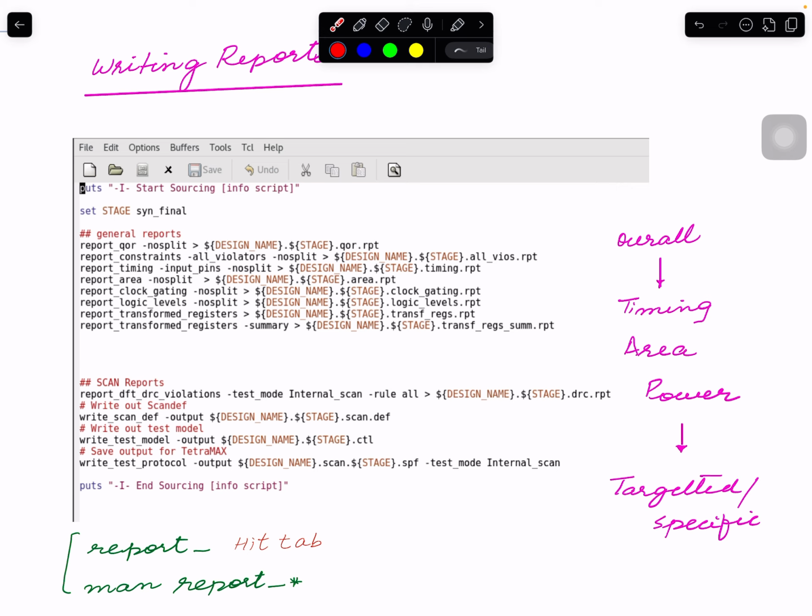Internal paths mean paths where input and output ports are not involved. Okay, input path group is the one from input ports to the flip-flop, and output path group is the one from the flip-flops to output ports. And then in between you have flip-flop to flip-flop. You can have flip-flop to memory, memory to flip-flop, memory to memory, blah blah. I'm considering all those as the internal one.